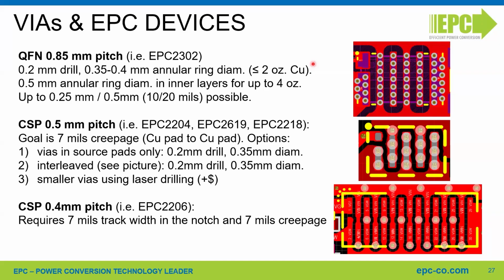So if there is space and if the features of the vias are allowed for the PCB technology and PCB manufacturer, it's highly recommended to use vias in pad. And they don't cost much more than vias out of pads. It's a technological adder, but it's also helping to make your design smaller, so most likely you use less PCB.